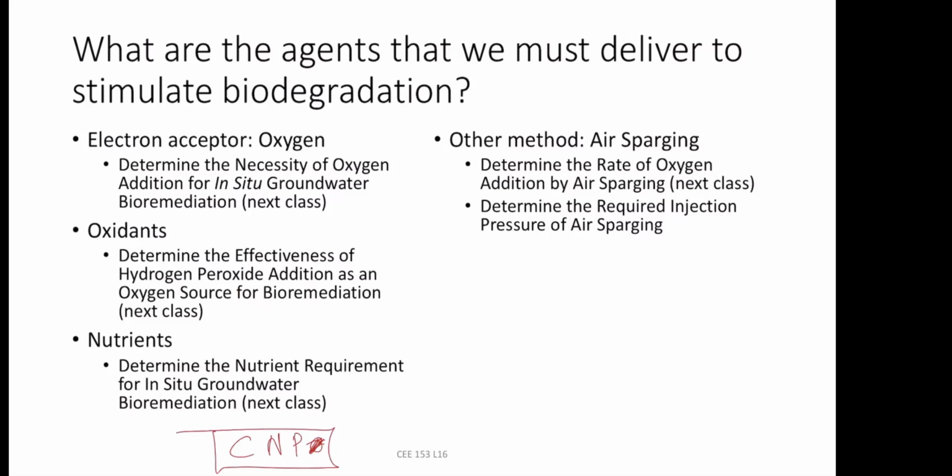So you got to have carbon, nitrogen, and phosphorus, everything. You can't just have nitrogen and phosphorus. Usually this carbon comes from the contaminant itself. A lot of times you may have to provide some extra carbon to stimulate the microorganisms, but you expect that this carbon is there from the highly contaminated site because of pollutants, which are organic. What you don't find is nitrogen and phosphorus.